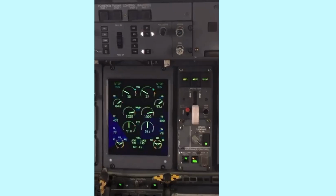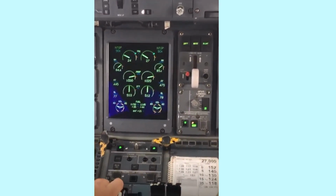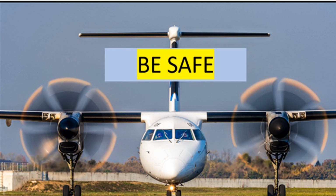But we know now that it's the autopilot. If the autopilot commands us to keep this type of torque with flaps 35 in this case, to maintain our VREF to VREF plus 10, we should do it as well, because that is what the aircraft's computer system is also demanding. So it's nothing magical, it's actually the autopilot. And you can see that we're coming there, and that's about it.